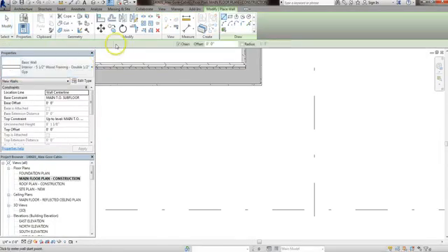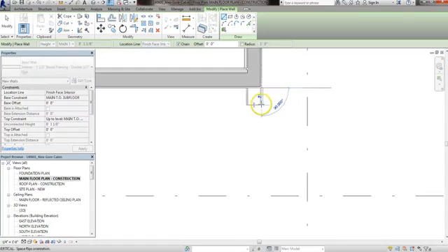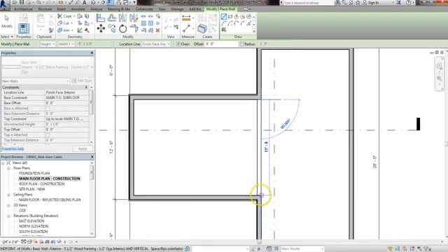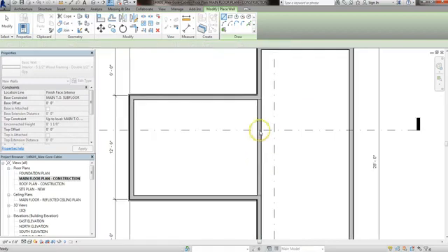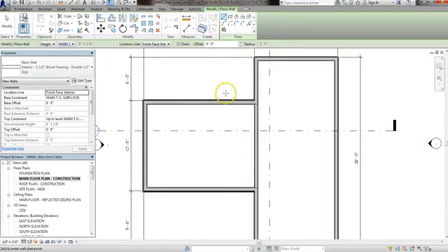So let's go to your walls. Let's do finish face interior. There you go. Hit spacebar. Connect those. That's a 5.5-inch interior wall, which normally you don't really need except for maybe plumbing walls. I put it there just to be structurally,